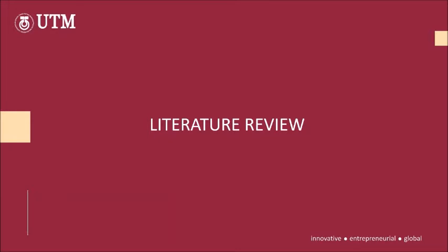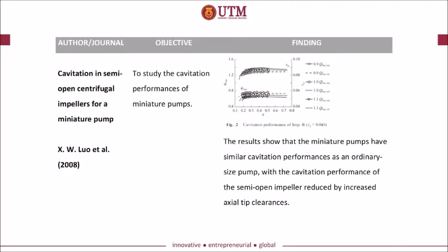Moving on to the literature review. The first journal that I have studied is the cavitation in semi-open centrifugal impellers for a miniature pump. The authors is XW Yu et al. In the year of 2008. The objective of the study is to study the cavitation performances of miniature pumps. The finding shows that the miniature pumps have similar cavitation performances as an ordinary size pump, with the cavitation performances of the semi-open impeller reduced by increased axial tip clearances.